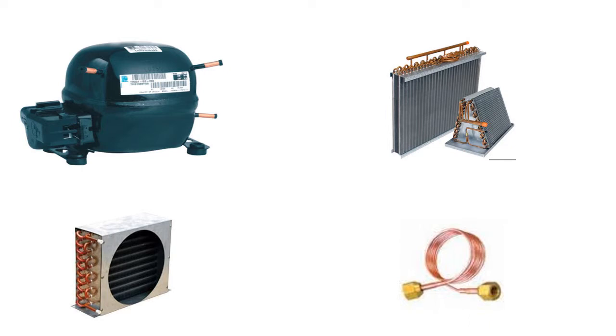The compressor is also part of the low side. It sucks the vapor from the evaporator and helps lower the temperature and pressure of the evaporator, so we have a temperature difference between the evaporator and the space being cooled. The next picture on the upper left is of a couple different types of evaporator coils. The purpose of the evaporator is to collect the unwanted heat from the space and to cool the air in the space. The picture on the bottom left is of a condensing coil.